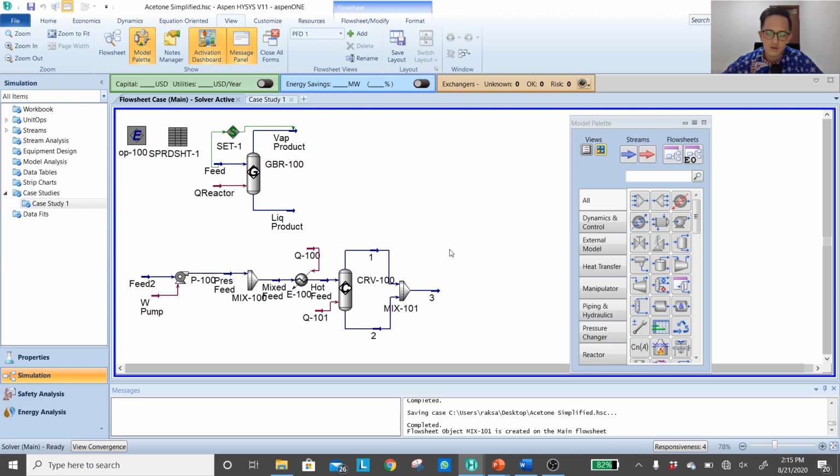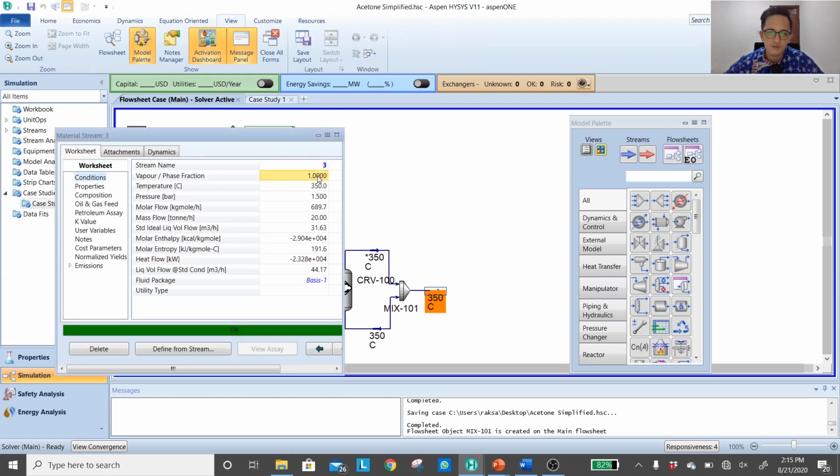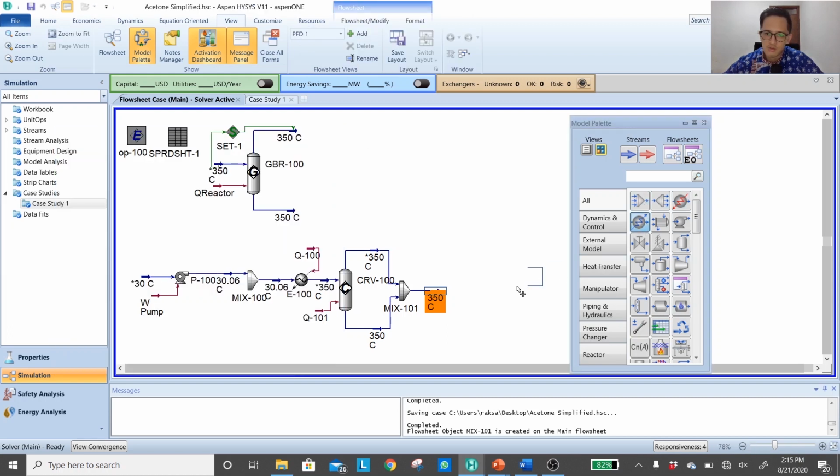Okay, so again, remember the block diagram. You can always switch back to the previous video or video 2A about the configuration. Now the main idea is to separate the hydrogen first using a single stage separation column. That means I will have to cool down my temperature, because now the temperature is still at 150 degrees C and all of them will still be in vapor phase, superheated. So I will decrease the temperature, so most of the compounds will condense while the hydrogen remains in vapor phase. So I'll put my cooler over here.